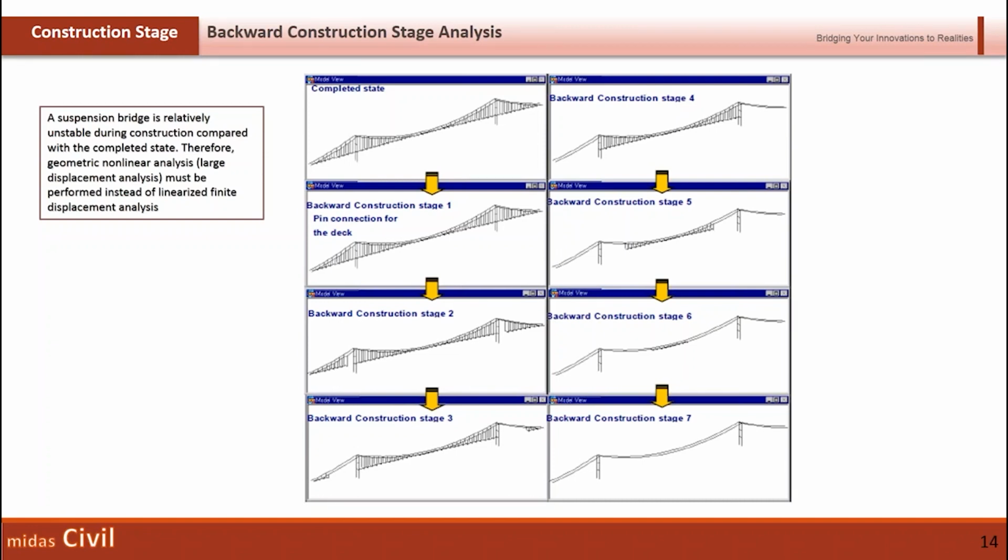So, the thing about construction stage in a suspension bridge is that we have to check how the forces are being redistributed from the beginning. Okay, so we have the completed state model already with us. So we go by backward construction stages.